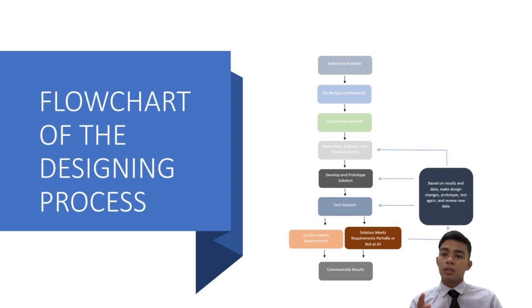Specify requirement. Calculation of the force as we discussed before. And then the bearing outer diameter to hold the shuttlecock must be lower than the diameter of the nose of the shuttlecock, and the inner diameter of the bearing should fit into the rod size based on the NTN bearing catalog. A 6x15x5 dimension is the most suitable bearing, as the rod is 6mm and the diameter of the shuttlecock nose is 25mm. It should fit the nose of the shuttlecock.